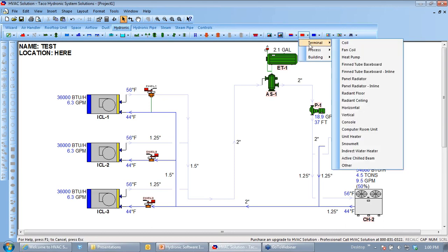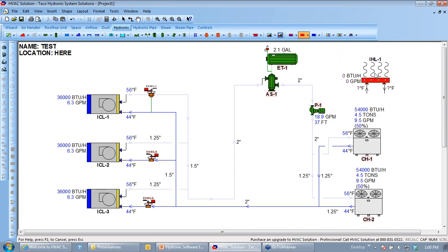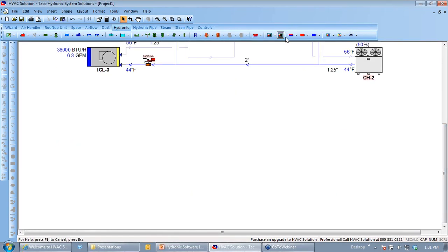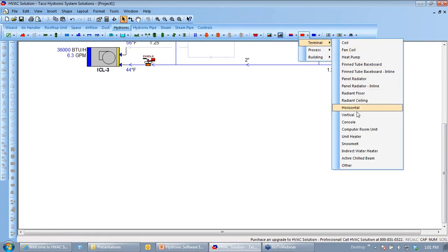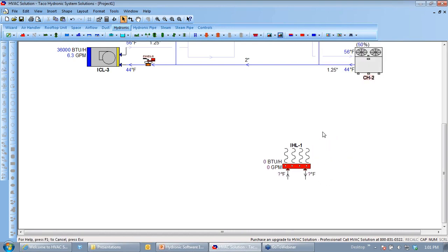For example, if I wanted to put in a snow melt system, I can click that guy here, drop him in somewhere, and I can also keep making this drawing larger and larger as I go down here, right? Keep tapping stuff in. Now I'd have to have a boiler drawn on here and everything like that. The snow melt system is just going to draw in for me. I'm going to connect him to my regular hydronic heating system. I know I've got a chilled water system on here right now. I'm just showing you as an example. I go tap him into those types of things, right?